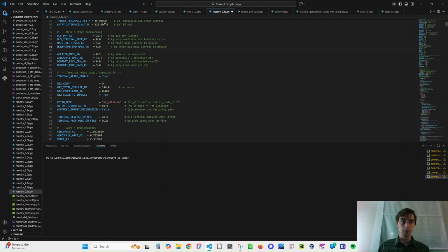Main chute mass, pretty simple. Because we also have a cutting option. Let's say there's an issue, or we just want to see what no parachute looks like. So we can cut it, and that decreases our mass, of course. And this crush device that I've talked about with this probe is a honeycomb pad. And that'll take a lot of our energy. Part of the computation is to know how massive it is, but it's also, more importantly, has a greater impact here.